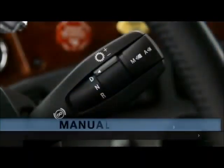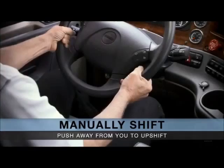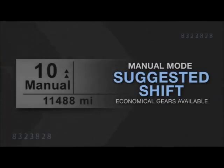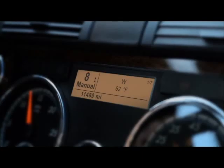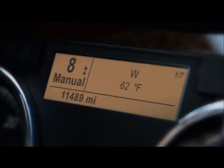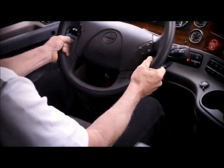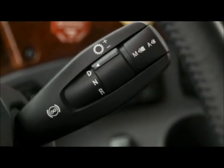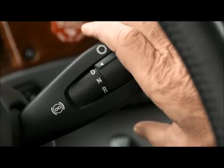The DT12 enables you to manually shift by pulling the stalk towards you to upshift or pushing it away from you to downshift. In manual mode only, a suggested shift is displayed to indicate the most economical gear available. The suggested shift is the number of up or down arrows from the current gear with a maximum of 2 up or down arrows. If you have 2 up arrows on the dash, you can pull the shifter stalk towards you and hold to upshift to the highest gear available. The same method can be used for downshifting in manual mode.